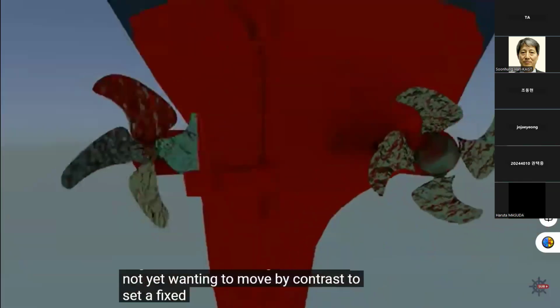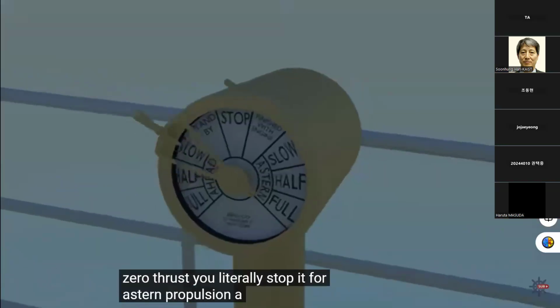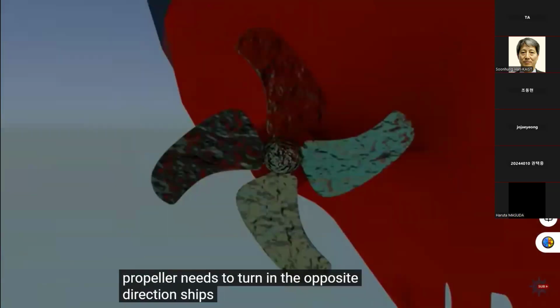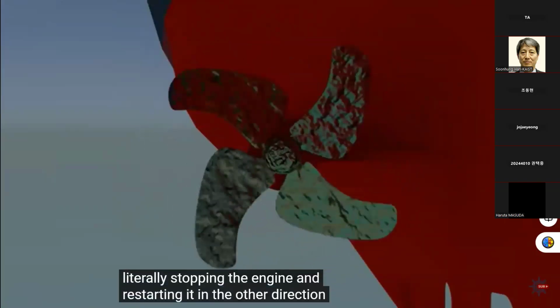By contrast, to set a fixed pitch propeller to generate zero thrust, you literally stop it. For astern propulsion, a fixed pitch propeller needs to turn in the opposite direction. Ships do this either through a gearbox arrangement or sometimes by literally stopping the engine and restarting it in the other direction.